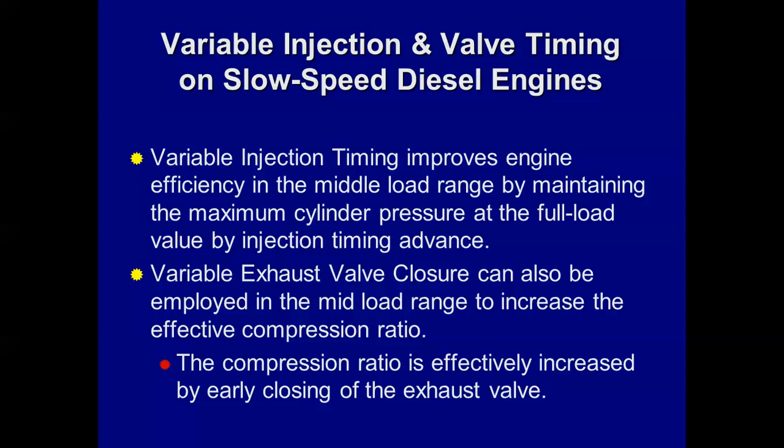So literally, depending upon the fuel that you're burning, the point that it starts to burn can change enough that you have to retime that engine depending upon the fuel quality and its ignition delay. We've talked about that quite a bit over the course.